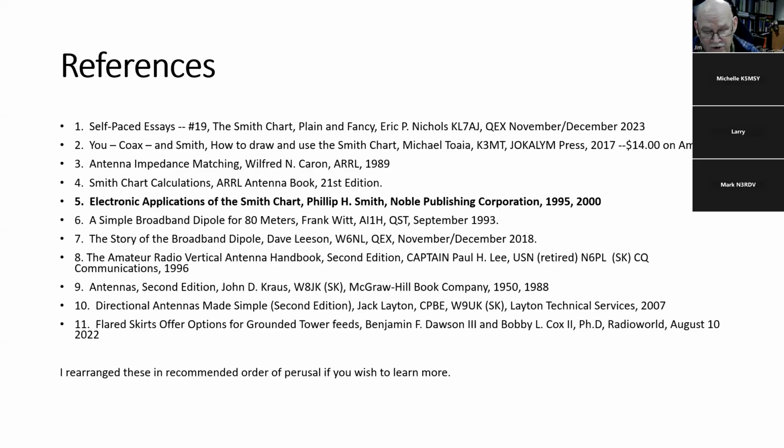You know, broadcast stations have to put down 120 radials of number 10 wire, quarter wavelength, and what I have learned in my research and in my limited experience is the more radials you have, the less it matters. At one point, I built a cage vertical with 16 radials on it that were very asymmetrical because of the shape of the property. And when I called a friend of mine in Northern Virginia, his response was, "My God, you're the loudest signal on the band."